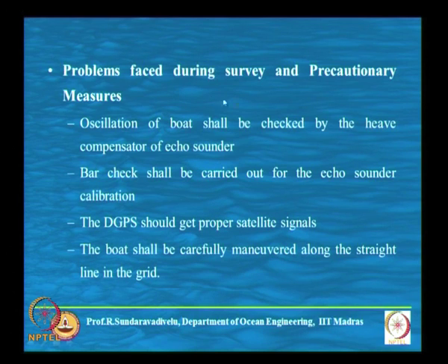So what are the problems faced during the survey and the precautionary measures? Oscillation of the boat should be handled by the heave compensator of the echo sounder. A power check shall be carried out, and echo sounder calibration is important; you have to do the calibration. The DGPS should get proper satellite signals, and the boat shall be carefully maneuvered along the straight lines in the grid. These are the various factors that are required.